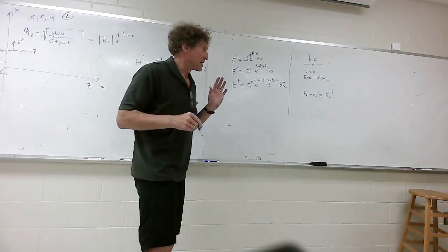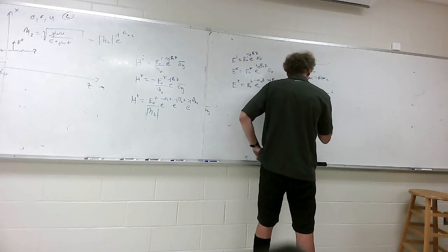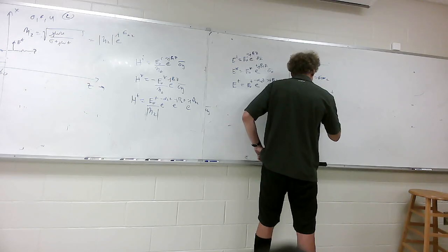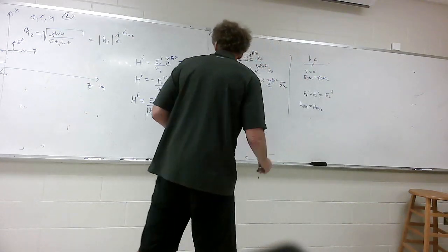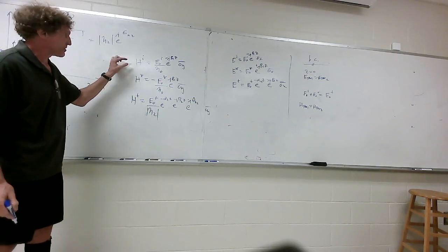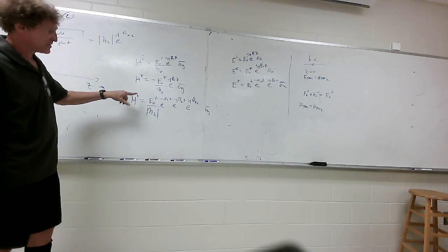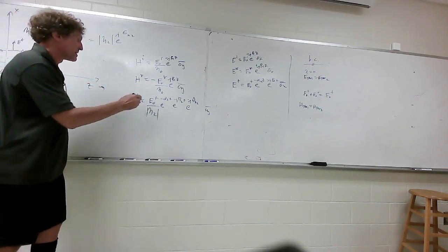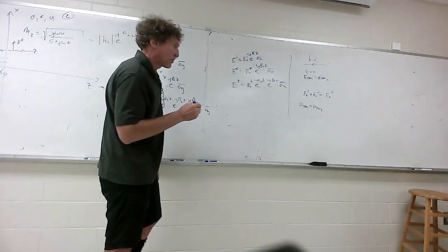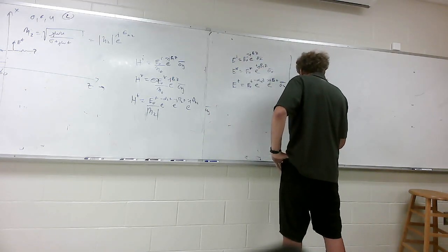Now, the next is H tan 1 is equal to H tan in region 2, correct? These are the tangent fields. I mean, the tangent fields would be at z equals 0. The incident and reflected would be on one side and the transmitted would be the other. You've got to take note of that negative sign. So over here, H tan 1 is H tan 2 means E naught incident over eta 1.